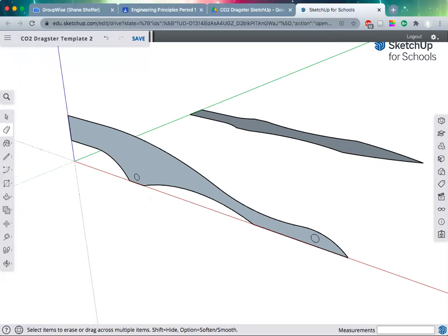So next, with step 3, what we're going to do is activate the push-pull icon. You can either push the letter P on your keyboard, or on the left side toolbar, you're going to select the 7th icon down from the top. It is going to be your push-pull icon. If you click it out, it's going to bring out your pull-out menu. It is going to be the first icon at the top.